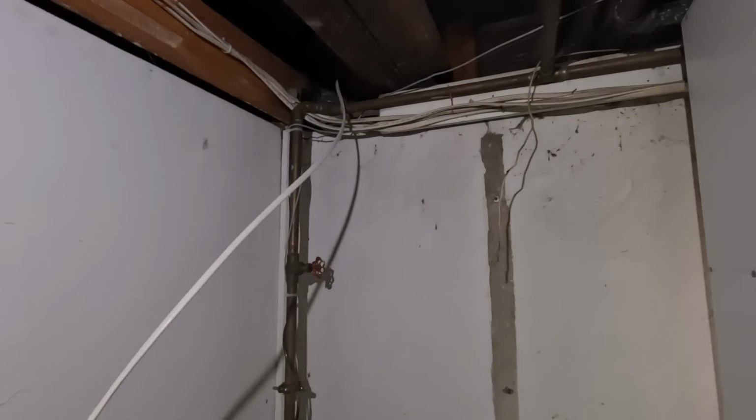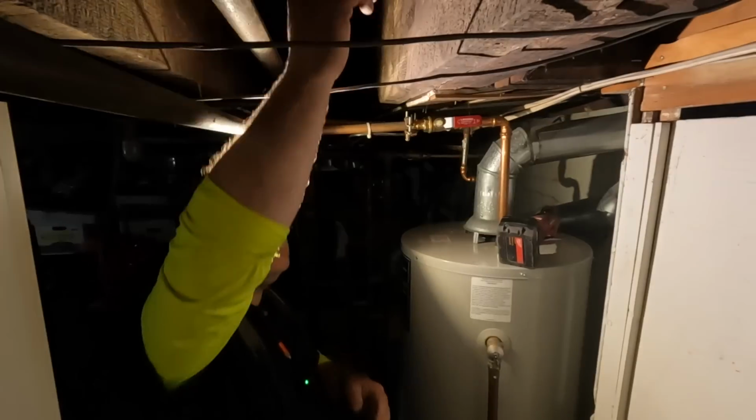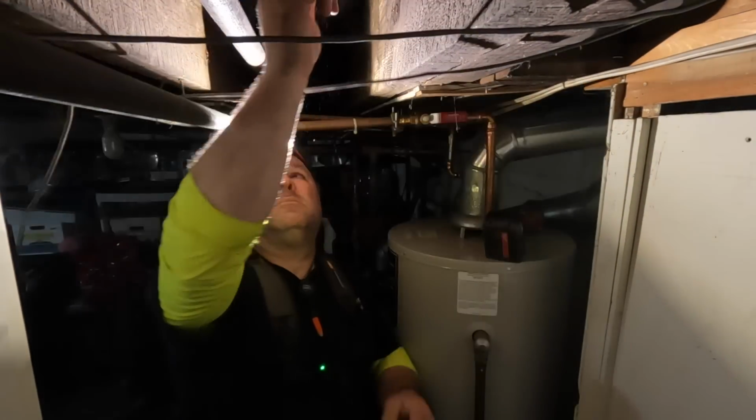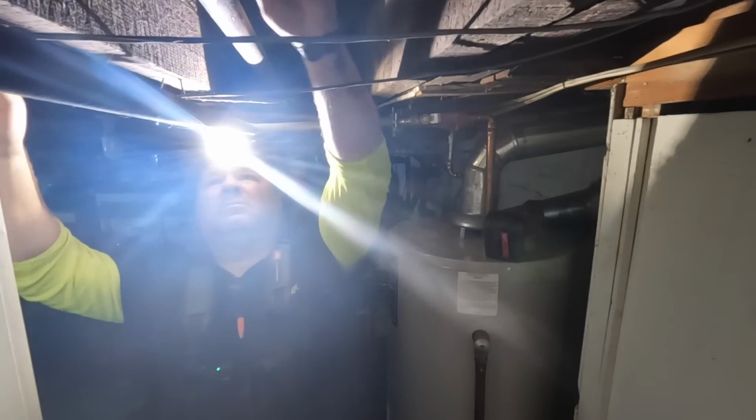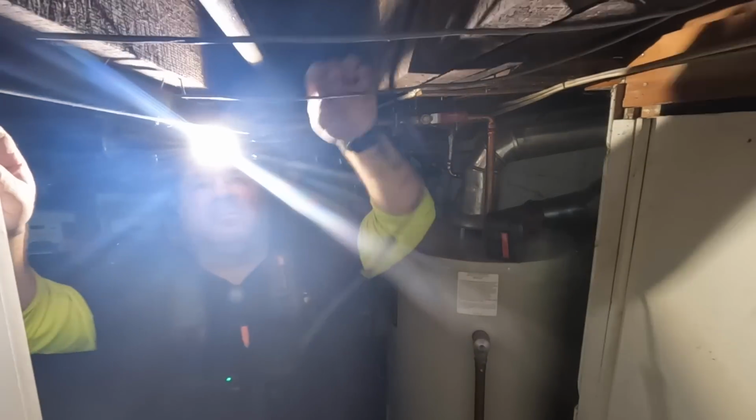This is your typical knob and tube. I do try to remove most of the tubes that go through the joist there. But generally the knobs, I'll leave those in place because they just make a mess. It's porcelain. You're going to hit it with your hammer, it's going to break, it's going to be all over the floor. Sometimes people specifically ask me to remove the knobs and the tubes. If they don't, then I just remove the tubes and leave the knobs in place so I don't make a giant mess. Totally okay because none of that's energized anymore by the time I'm done.